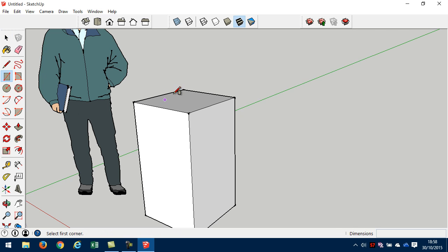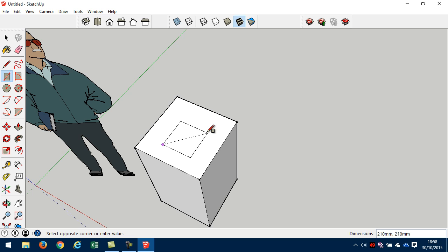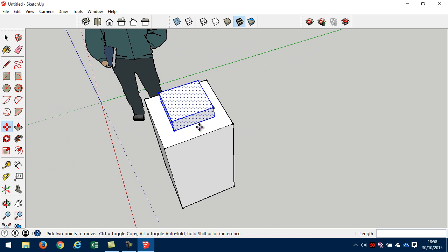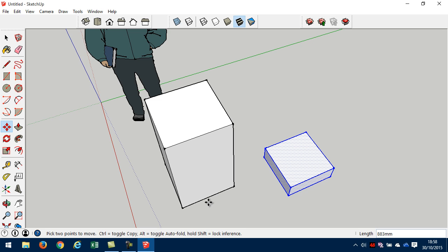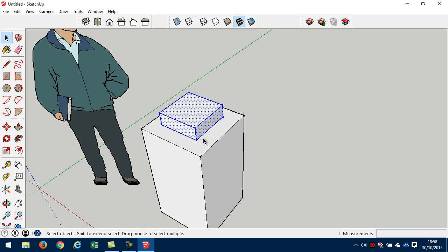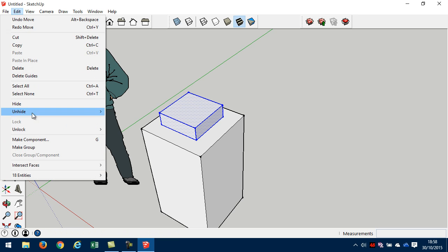So if I do a square there that was 300, 300, enter, and then extruded it by 100, enter, and if I triple clicked it, it only selects that object. So I could move that, and I could even move it off of the object, so it's separate from the pedestal. Okay, so let's actually leave that, and I'm going to make that into a group as well.